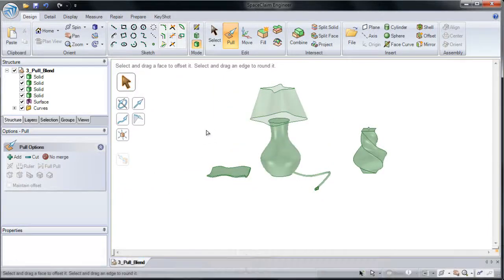So in this section, I'd like you to try out the different blend options and blend through the different objects. Blend through points to create a curve, blend through edges to create a surface, and blend through surfaces to create a solid. And also use takeoff vectors, periodic blend, and ruled segments as you do this.